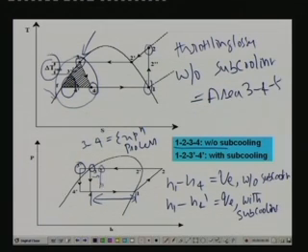So at the inlet to the expansion device you may have vapor. We shall see later that this will actually lead to the malfunctioning of the expansion device. An expansion device is designed to operate with liquid entry only; it should not have any vapor. So the possibility of vapor going into the expansion device exists if you have a cycle without subcooling. But if you have subcooling, there is sufficient margin, so even if there is some slight change in the condenser heat transfer, the inlet condition can still be in the subcooled region. So this is the second benefit.